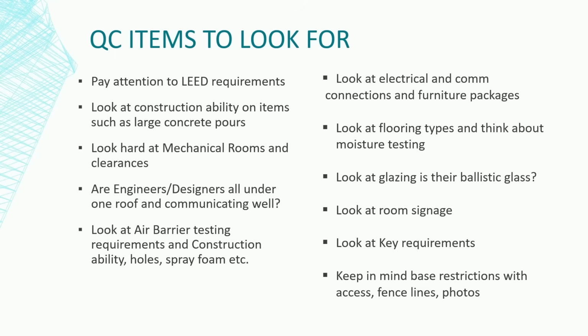You need to look at clearances around all the electrical panels. You need to pay attention to the VFDs. You need to pay attention to filter access for filter replacement. I don't know how many projects I go to start commissioning with teams, and they've got zero or no access to filter banks. And that is just not acceptable. And then they're ripping out and they're redoing. So please pay close attention to those mech rooms when you're sitting at that table with the engineers.